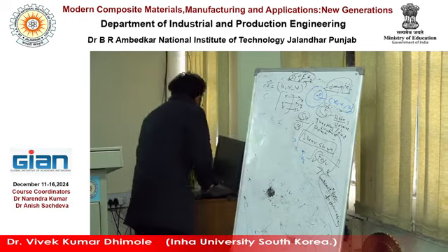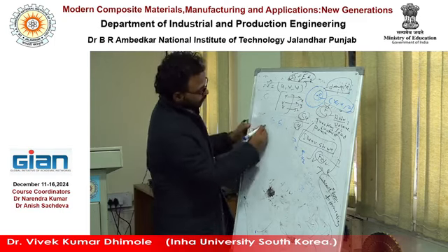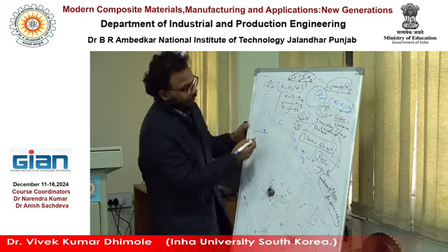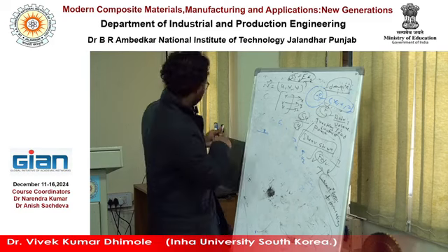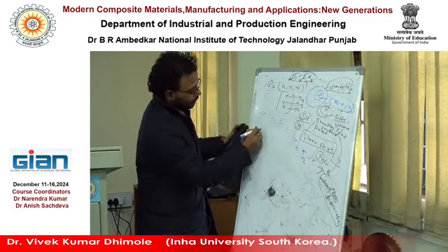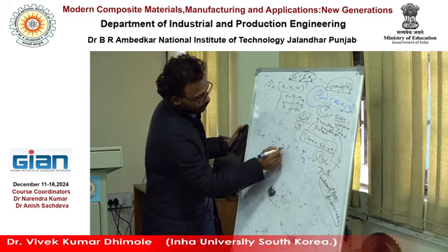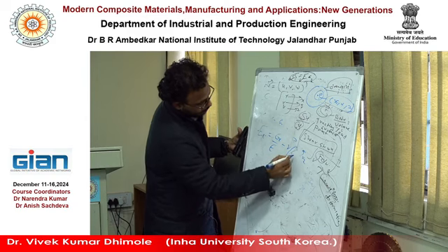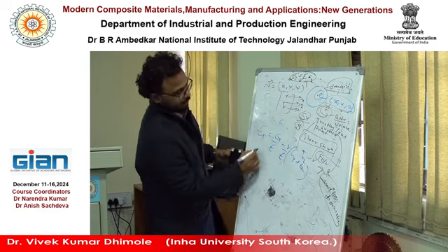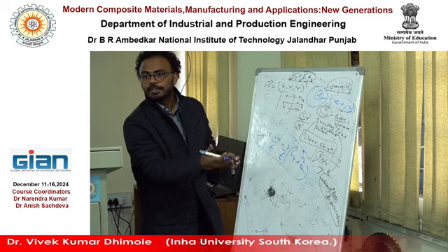So we have a force now. Strain, you understand, let's do the force summation. So we have sigma x. Suppose you calculate the strain this way, and that has a relation. Strain has a relation with stress this way, right? Epsilon x is equal to sigma x upon E minus nu times sigma y plus sigma z upon E, right? This is the formula to calculate stress and strain conversion.